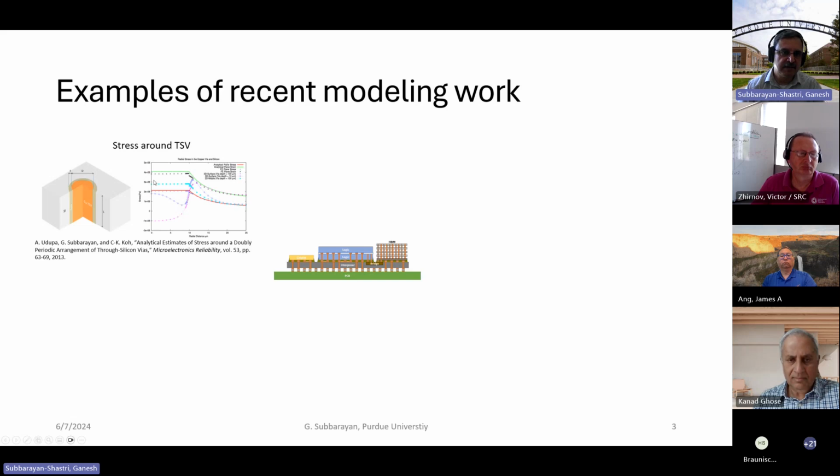Here, these models that you see, these dark lines, are analytical solutions. And what you find is analytical solutions do really well if you can spend the time. It takes time. Like you said, this is a PDE, and I need to analytically solve it. It's an infinite series. I truncate the series to some number of terms and get a solution. It's actually as good as you can get with a finite element solution. It's worth investing the time to do that.